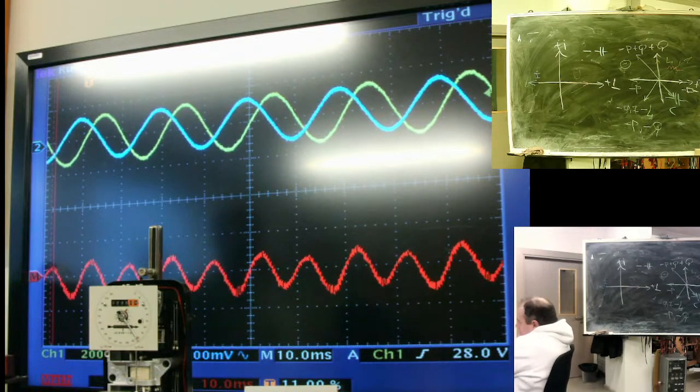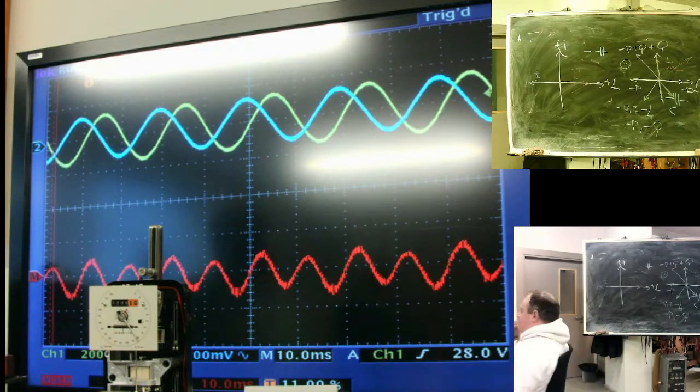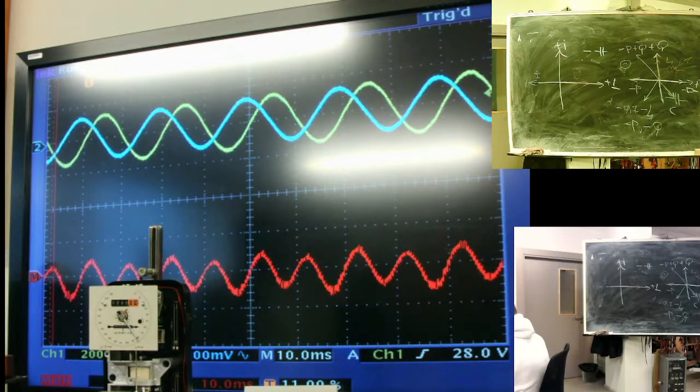When current leads, when voltage is lagging, you have only two choices. Coil or capacitor? Capacitance. So, what kind of load do you have? You have 0 watts, you have minus 70 watts. 0 watts means that there is no resistance. Current leading, so you have a capacitor attached. Yes.